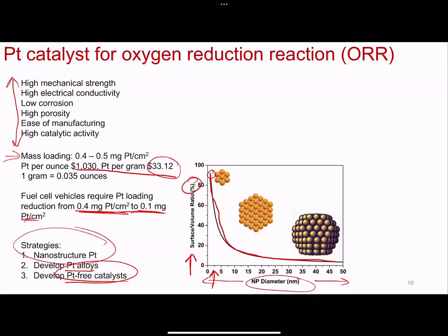But if you have a newer car, platinum, palladium nanoparticles are already loaded on cerium dioxide, and that is what is converting carbon monoxide, oxidizing it into CO2 so that your car can meet emission standards. So you're not just pumping carbon monoxide into the air.